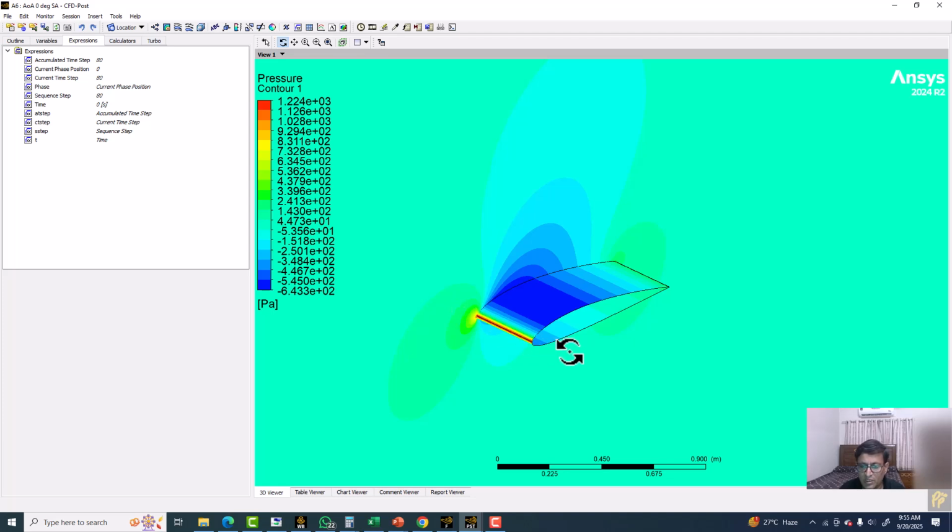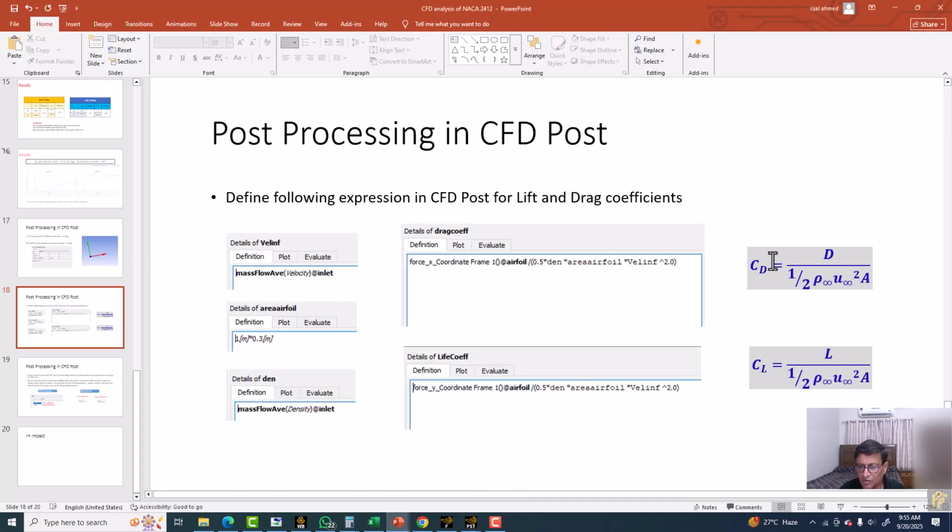For example, if my new wing is 1.3 meters, then I will multiply with the 1.3, I will multiply with the 0.5, and the same thing here. So if I want to get the drag force for some other aerofoil length and area, I will simply multiply the CL and CD by 1/2 density, velocity squared and the area, and I will get the force for that particular dimension, the particular material properties and the flow properties.